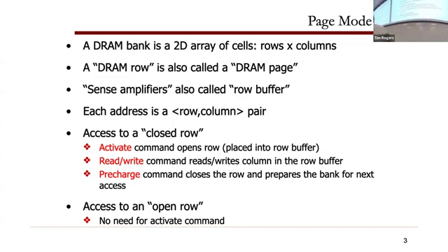So we first have to activate that particular row. There's an activate command, and there's timing associated with this for whatever flavor of DDR you want. After that activation command, the value is placed on the row. Then you need to read and write each of the individual columns, because you need to read out some piece.